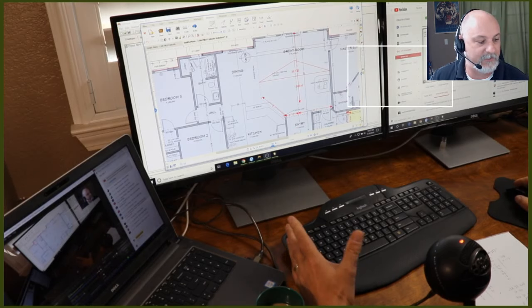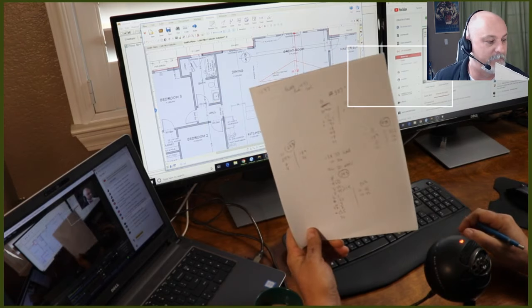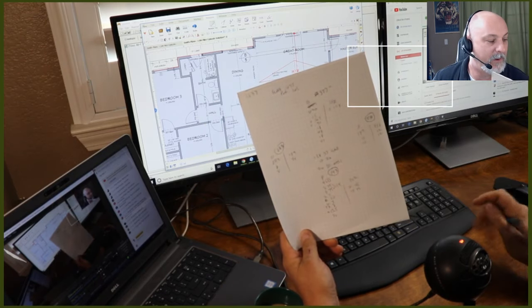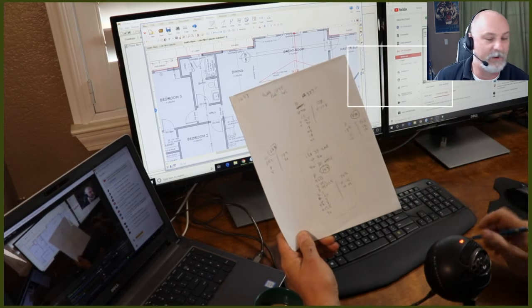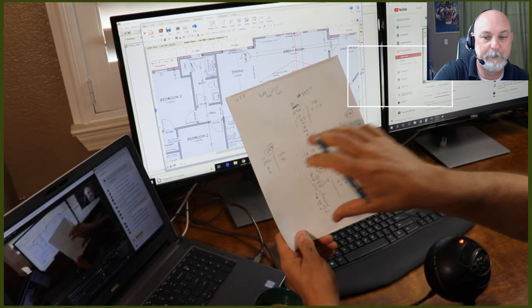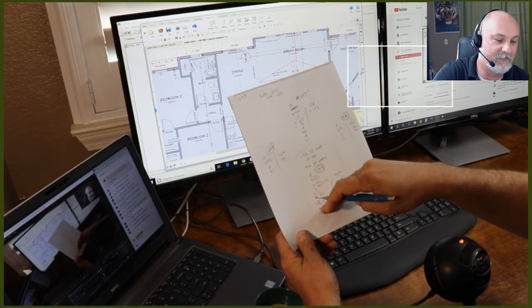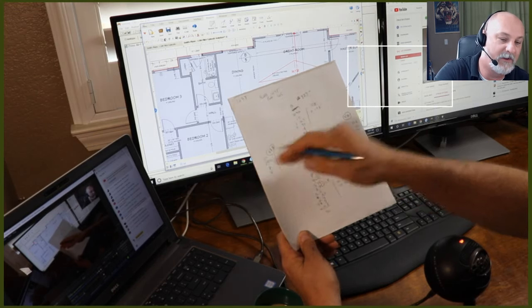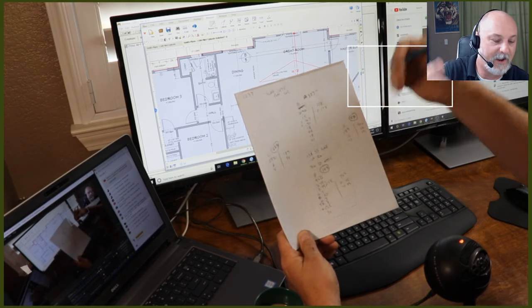And just to give you an idea here, I'm going to do my over-the-shoulder camera shot here. And you can see what I'm doing. I just do my takeoffs on a simple piece of quad paper. I orient my information based on the relative page layout. So my front takeoffs are on that portion, my left takeoffs are over there, my rear takeoffs over here, and my right takeoffs over here. Just keep it real simple.